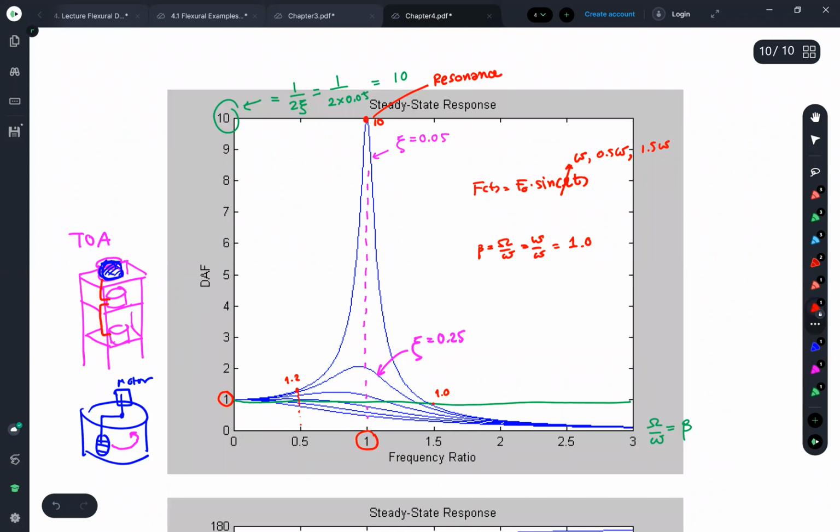This is the way they produce it. But the danger is that every morning when they start manufacturing, they just push the button, and every motor starts together. You can imagine they go with the same frequency, right? And it makes the building vibrate. For example, in this direction very largely, and they're afraid the steel frame will collapse.